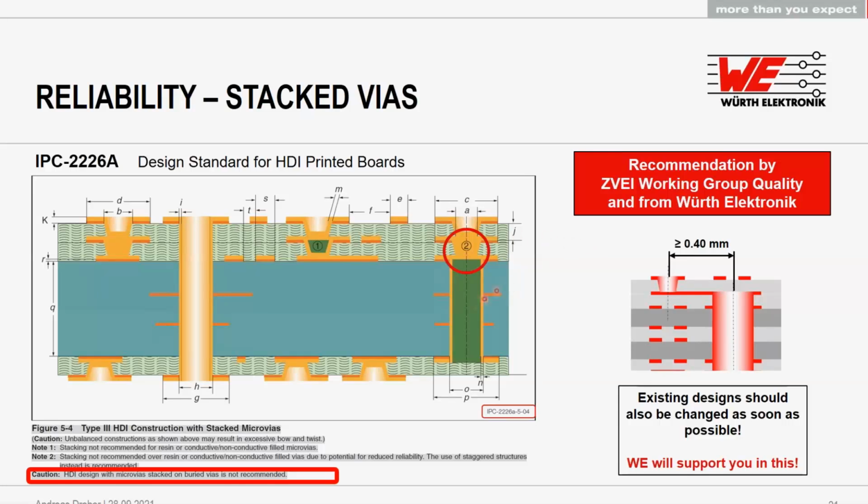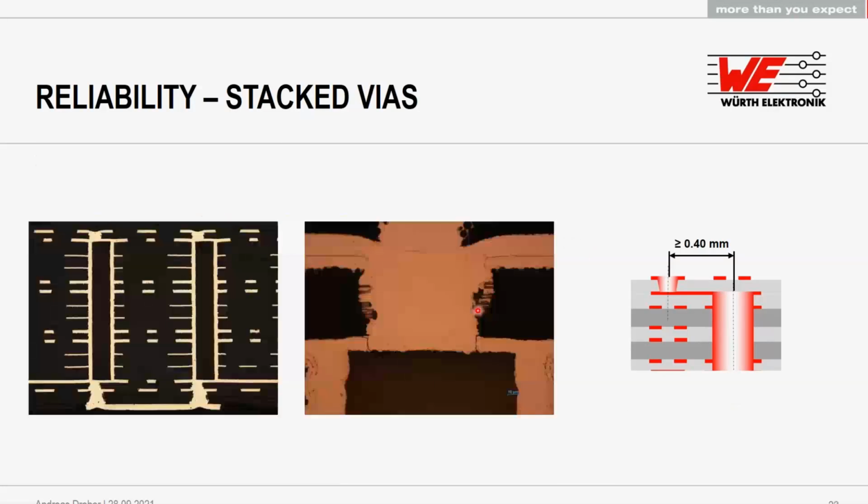What can happen here is through the material change. We have seen it before. The microvias are directly linked to the buried via, and the microvia will get the whole stress in this thick board, which can relate to cracks and so to failure of the boards.